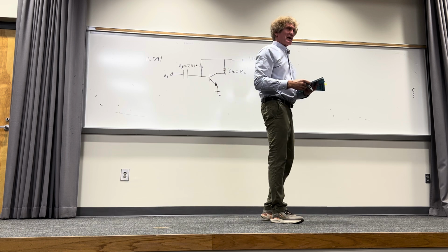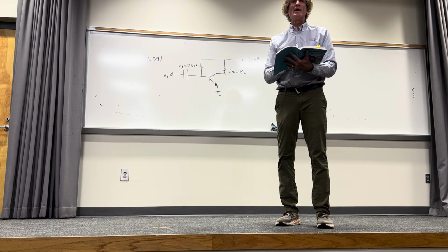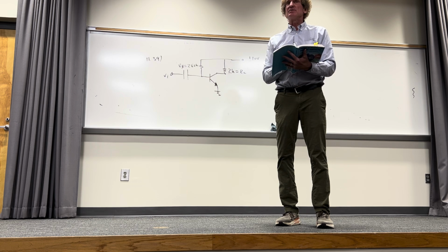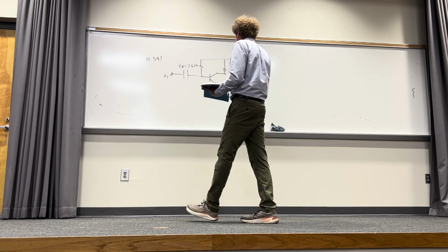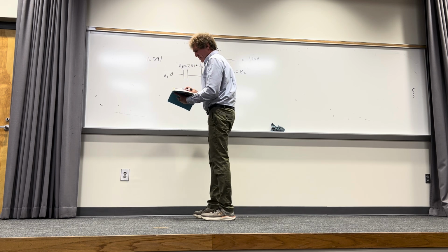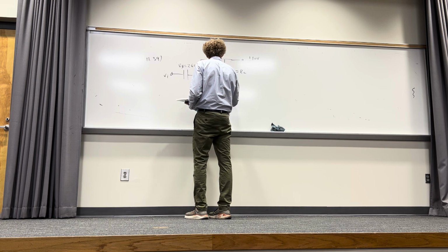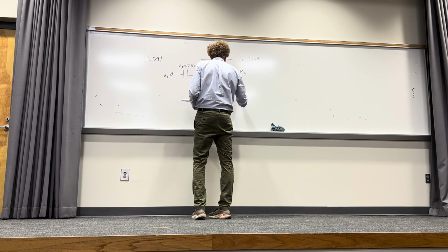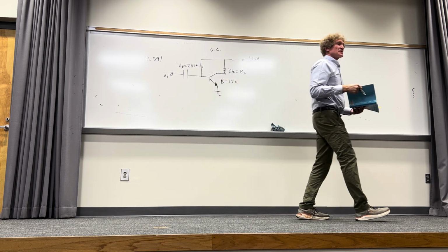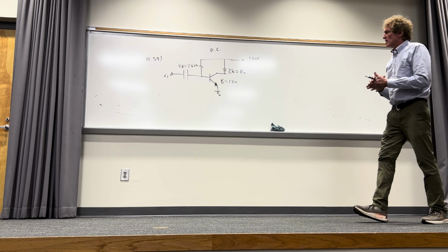They have a thing, and they have a statement, just listen to me. They say, determine the Q point. That's called the quiescent point. It's what values of current and voltage would occur in this circuit. Y'all hear me? Now this is called DC analysis because there's nothing time varying. I'll get to it more. And what they want is this, and they say beta, or the current gain in this one, is 120. All right, so everything here is extremely reasonable, common, something you might run into in terms of values.